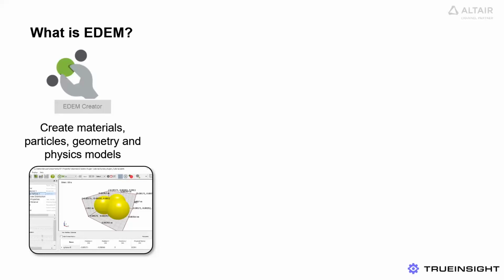And in the screenshot shown here in EDEM, you see a multisphered particle. Often we recommend using a multisphered approach for solving DEM simulations because of their computational efficiency. I also want to point out that EDEM has the capability of using polyhedral particles, single sphere particles, multisphere particles as shown here. And in the 2023 release of EDEM, which is imminent, we will no longer be restricted to solving with only one particle type. We'll be able to mix all of those particles together in a single simulation.